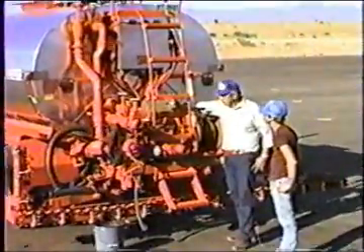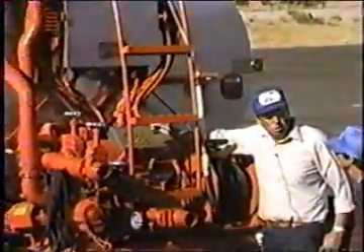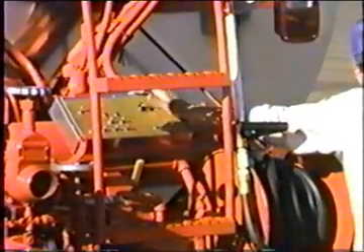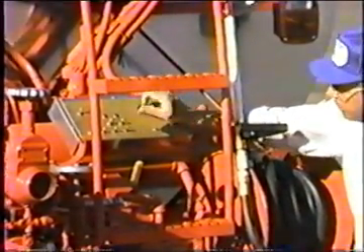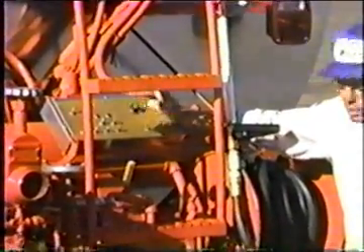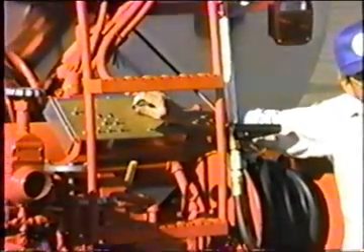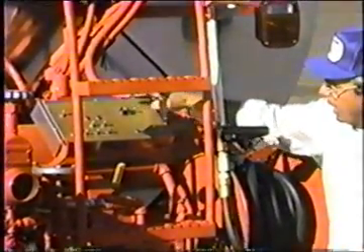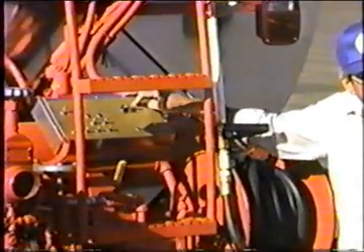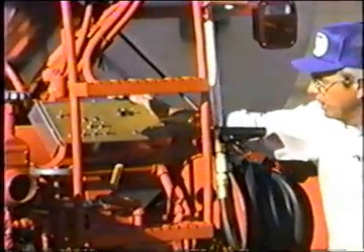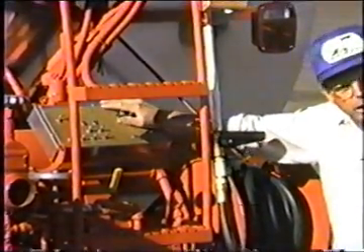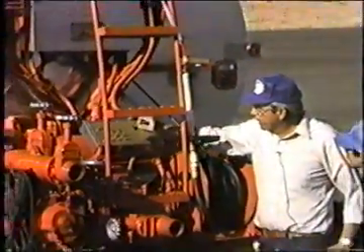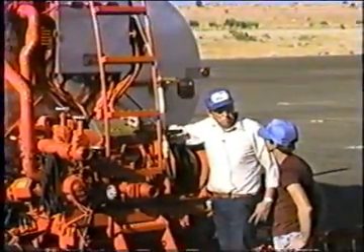In order to use the rear pump control, you have to leave the front pump control in the manual position. You have to leave the speed turned clear down. This is just like the volume on your radio. When you turn it to the left, it's down. When you turn it to the right, it's loud. And you have a forward reverse control. Okay, in order to use the rear, you've got to leave the front in manual, turned clear down, and in the neutral position on forward reverse.